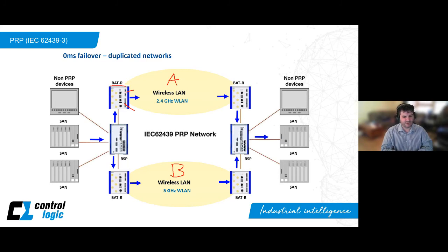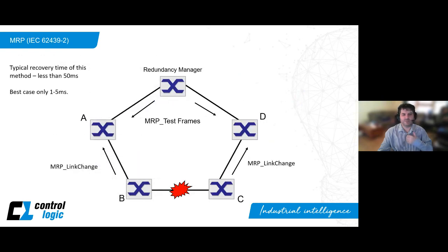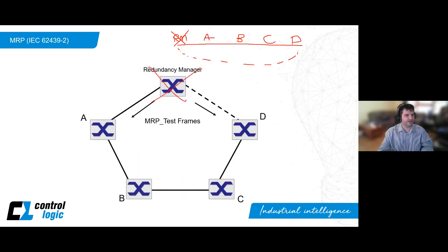And we've talked to some integrators who are working on typical mining applications with stacker reclaimers, taking advantage of using PRP so that when the fiber slip rings have issues, they have a redundant link in place already to take over the communications. And similarly, when people have upgraded networks, so they have existing equipment that's being put in, some people have used PRP to take advantage of what they're putting in and what they used to have so that they don't have to just pull out the old equipment and throw it in the bin. Outside of that, MRP and RSTP are used pretty much everywhere. So they're not application specific, they're more general purpose.